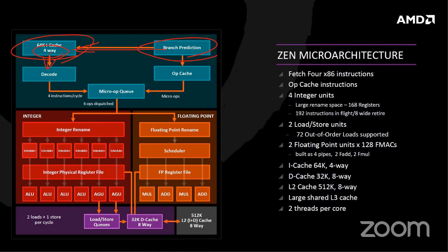After you fetch an instruction, you decode it. And again, after you decode it, it will be in the micro op queue. This micro op is a different micro op instruction set architecture, but it's the same concept. You just decode, or say rewrite, your x86 code into micro ops like RISC instructions inside this processor pipeline. And again, they also have register renaming units for floating point and integer, and they have their own schedulers into different pipelines.